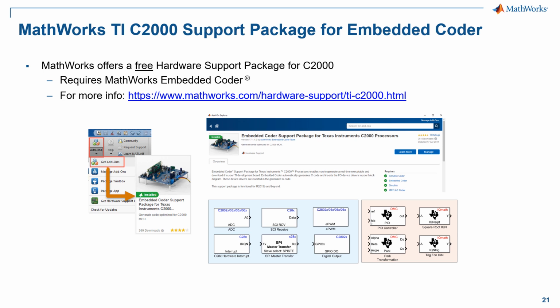And personally, I have experience with customers who are only interested in generating algorithmic code and they want to integrate it into their existing legacy C code of their I/O drivers and serial port transmission. We also have customers who like to generate the entire code, including the I/O driver blocks for PWM output and ADC digital I/O feedback. So inside the library of the TI C2000 support package, we also have many choices of optimized blocks for generating efficient C code.